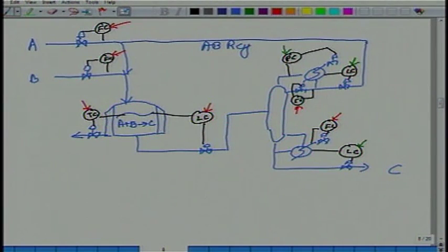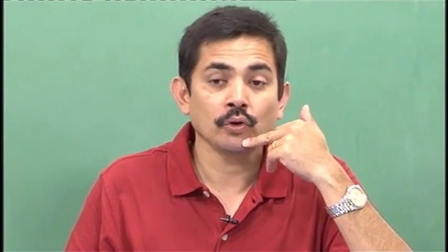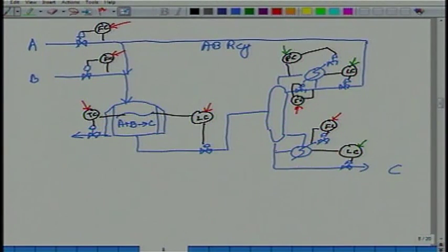Management says, well, this is only 95% pure, we want 99.9% pure, we do not like this, please operate your process so that we get 99.9% pure product, okay. What does the operator do? He looks at the process, figures out, well, there is too much A dropping down the bottoms, let us say. So what does he do? He increases the steam.